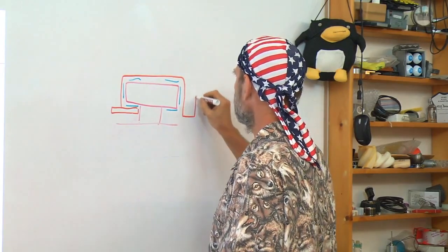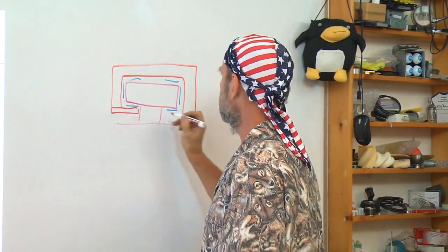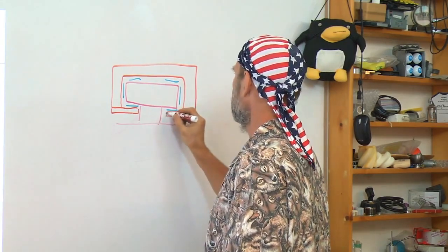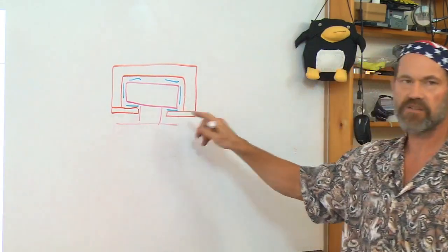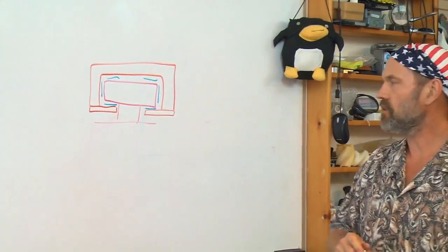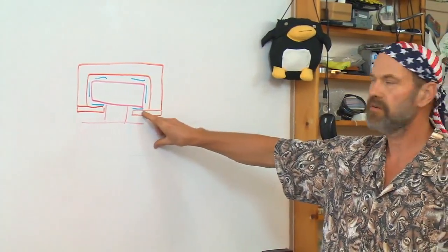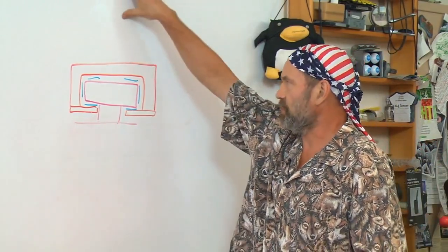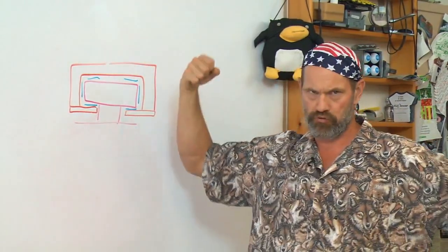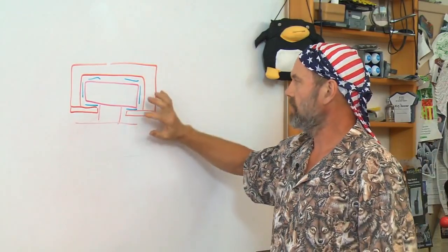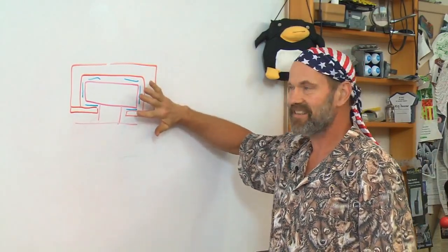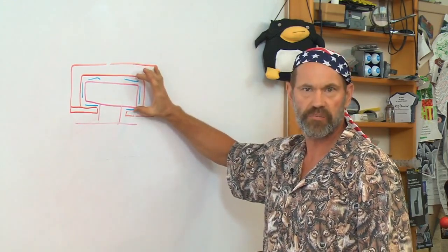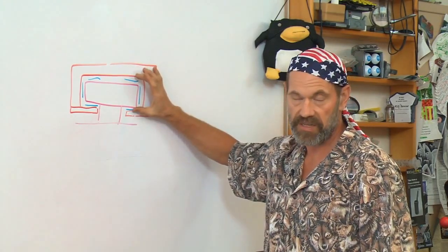Here's a very good thought question for you in a minute. Why did I draw these lower guys real thin? These are called keeper plates. For a machine tool slide, if I have big giant loads up top, why do I have these soft little keeper plates? These act as springs to keep this whole thing preloaded together, as we'll talk in a minute about the importance